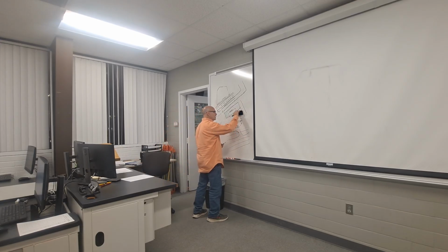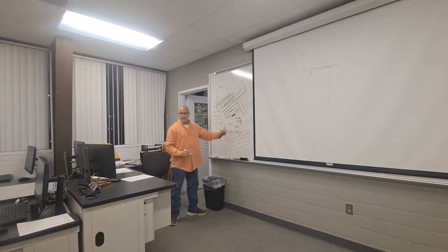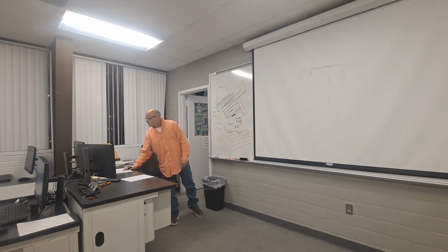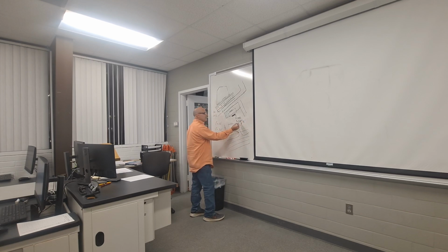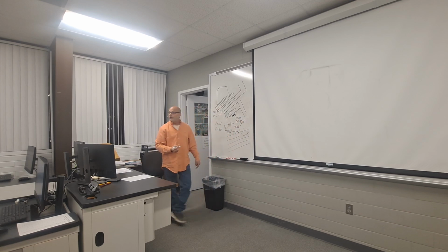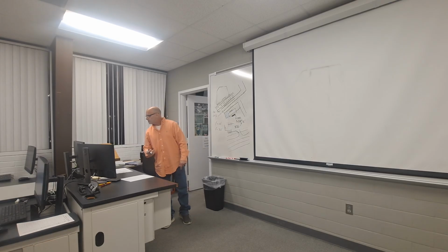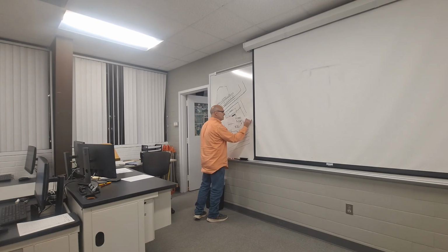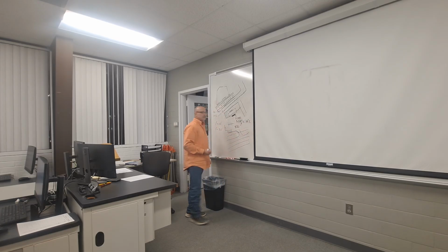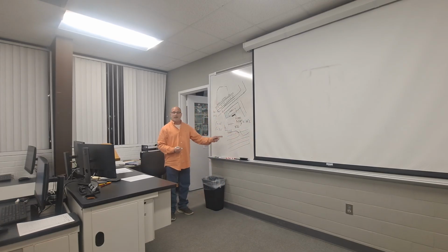So if I'm typing this in and telling AutoCAD to draw that line, I'm going to type it in as S08D. Don't label your drawings with that though. So it's south 8 degrees, 16 minutes. Even if it is one character right there, always show 2 for your degrees, minutes, seconds. Just like I wrote 08, not 8, always show 2 characters. South 8 degrees, 16 minutes, 18 seconds, east. That is how that number would be labeled on your drawing.